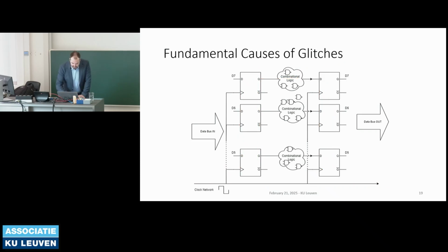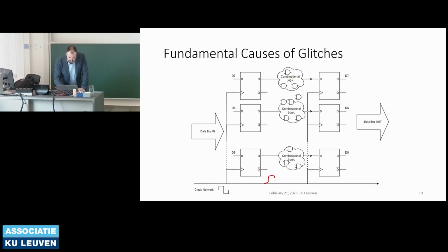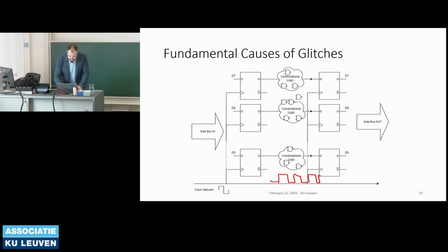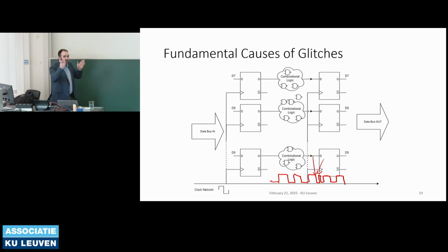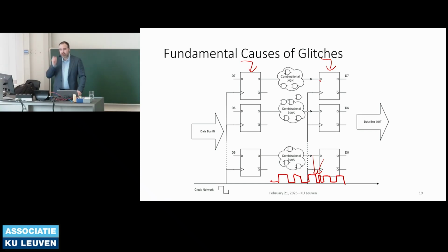One way is that we're supposed to have a nice clock signal like this, but you could insert weird clock signals. So a normal one and then a short clock pulse there. Suddenly I have this very narrow clock, and data won't have time to actually reach the second stage of the flip-flop. So I've purposely introduced a very narrow clock pulse that's going to introduce incorrect data.